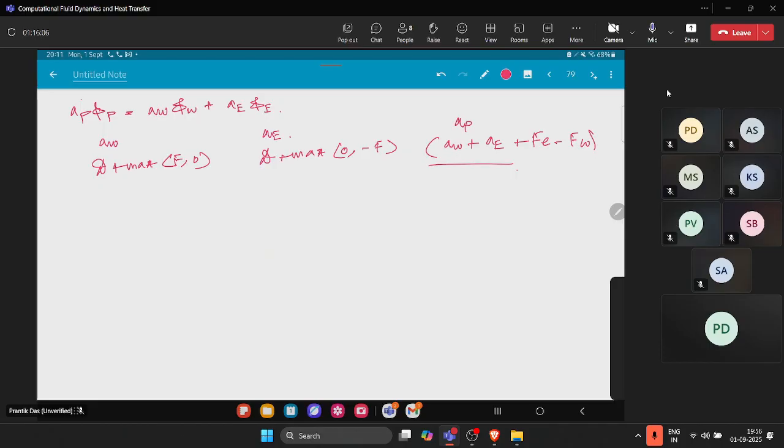So you can use this max function in your program also, and that's why I've written it like that. As I've shown you how to solve the convection diffusion problem using the central difference formula in the previous class by using Octave, if you want to solve it using this half-point scheme, you basically have to change the values of A, AW, and AP, and then you can create the same program for the half-point scheme. The whole thing remains the same.